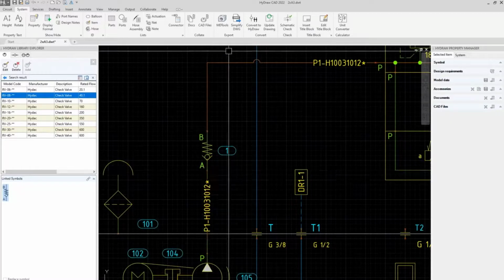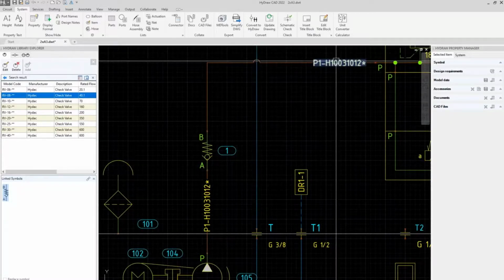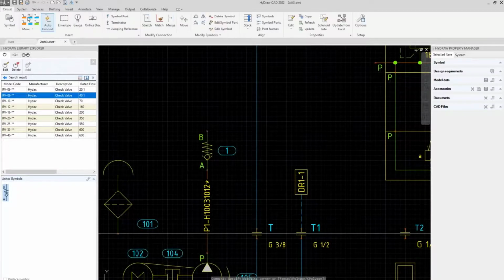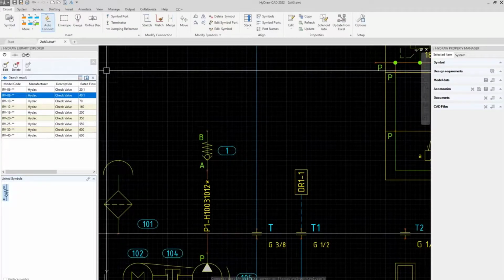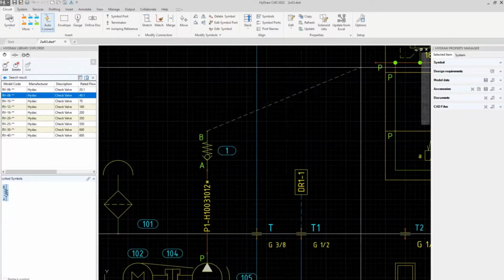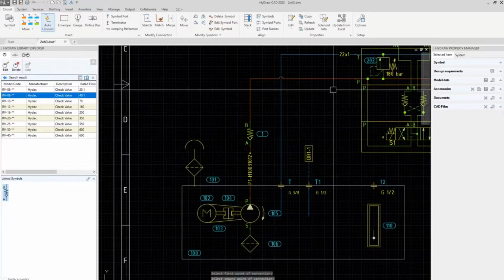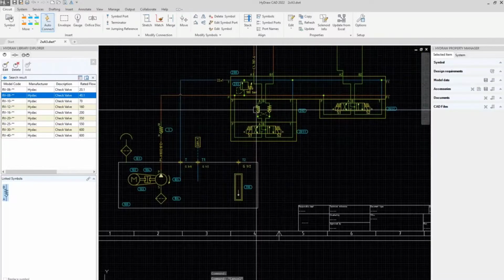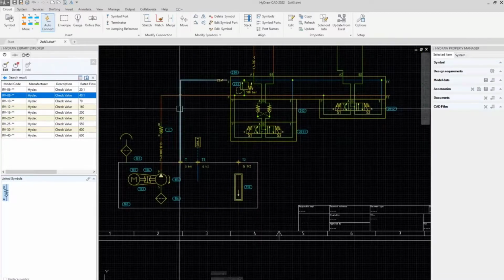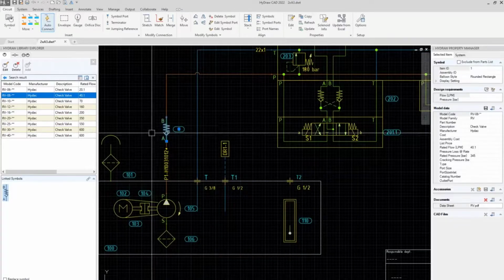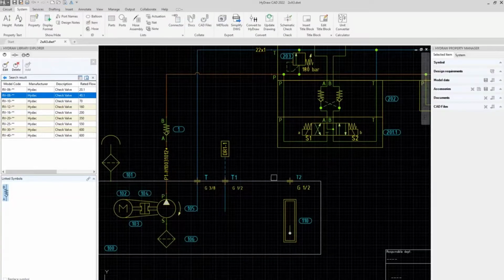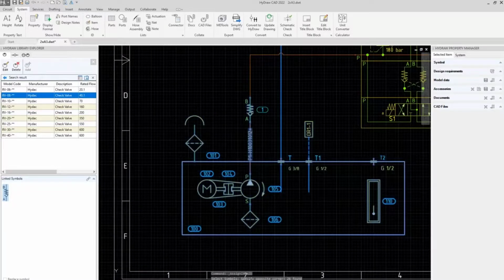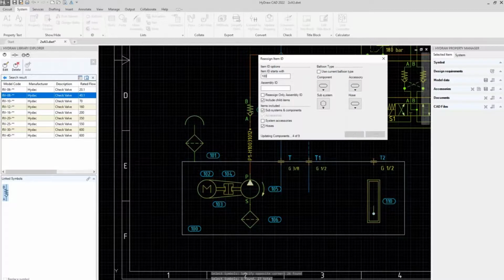In this case, it probably does not make sense to have 2 of the same. So usually that check valve maybe we represent it this way, so we directly fit into the fittings of the subplate. Again, this one now is not part of anything, so we can just renumber items. Item, all the power unit, including my valve 1, and we start numbering from 100.